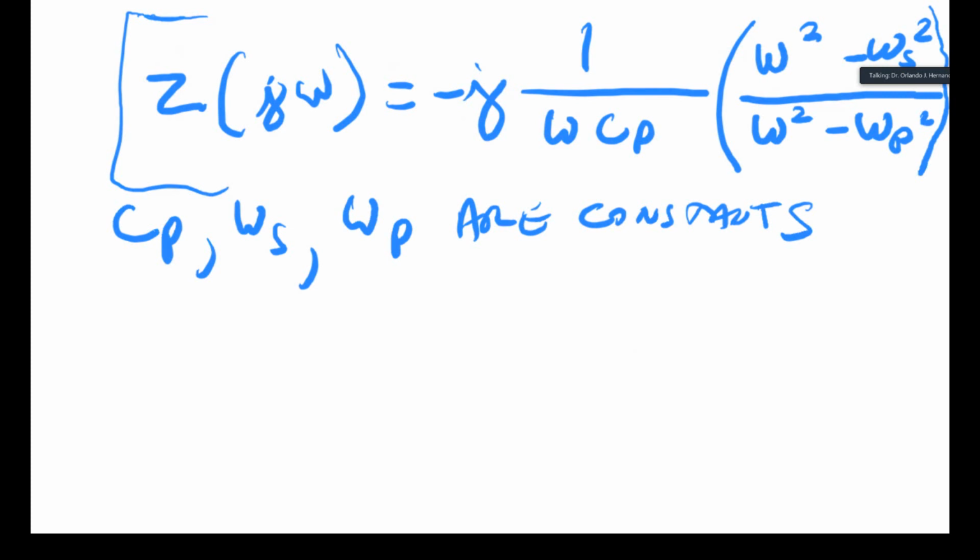So the most common oscillator is what you find in all kinds of digital chips and microcontrollers, which is a simple inverter. An inverter can be seen as a very high gain amplifier. So it's a simple inverter, and maybe you have a little bit of loading resistance in the inverter, and then here you have your crystal.